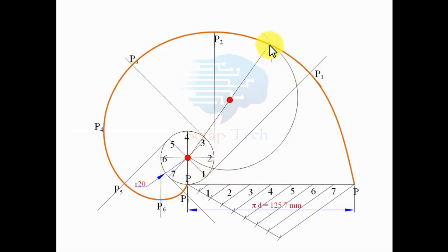Done. Now this particular semicircle, you see guys, is intersecting this circle's circumference somewhere here. Let's make a point over there, and when you join this point with this point over here, you're going to have a normal, and you know very well how to place a tangent. A line perpendicular to a normal automatically qualifies as a tangent, something like this. It is going to just touch this curve also. That's the tangent.